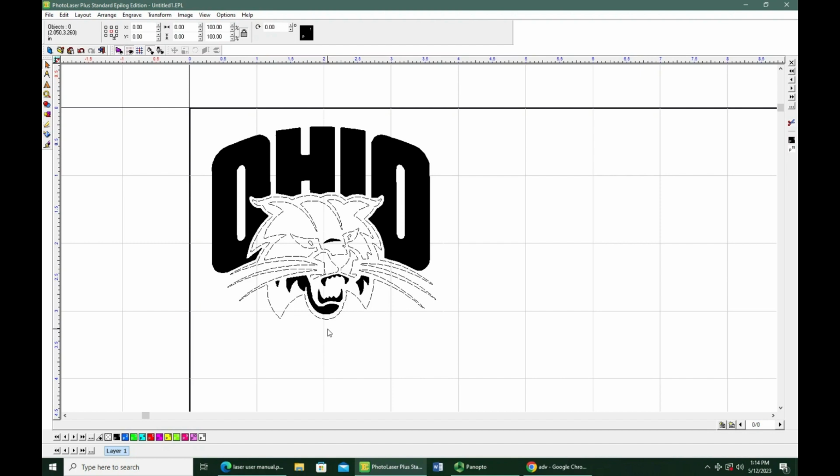When you switch back and forth a lot, sometimes you end up with layers underneath, and you might have it raster a section and then come back through and engrave or cut that section. So you want to make sure everything's in the same layer. If you're sending it to the machine and you end up seeing that it's going to raster an area and then it comes back and then it vector and cuts it, that's just wasted time. So you need to readjust your file to get rid of it.